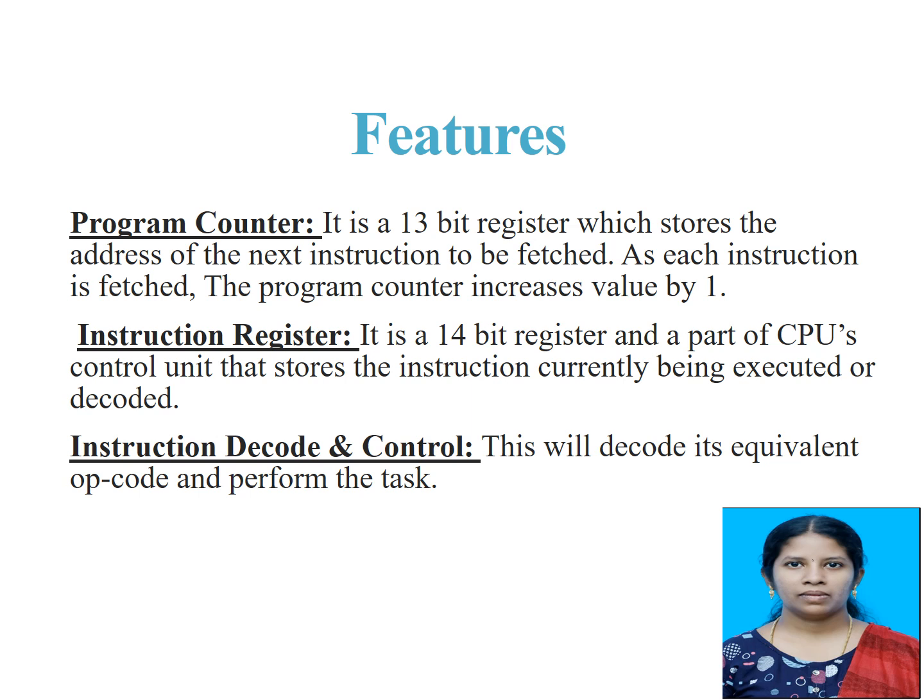Instructions like goto, call and return can directly modify the program counter to jump to a different location in the program. The PIC microcontroller has 8K of program memory, so it needs a 13-bit address, with the lower 8 bits stored in the PC low, that is program counter low, and the higher bits stored in the PC latch.